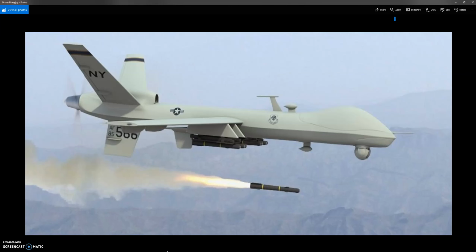And then we're going to create a plane. We're going to create a plane on the front. Let's flip that around. Flip offset. And then this is the plane we're looking for. Okay. And then let's sketch on the plane. Create a sketch. Turn it around. I kind of like to design sometimes from this way to that way.